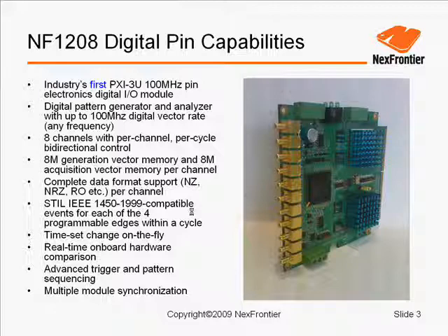IEEE 1450-1999 compatible events for each of the 4 programmable edges within a cycle are supported as well. We are able to do time set change on the fly for this module. Besides, this module is able to do real-time onboard hardware comparison for DUT data that is being captured. It has advanced trigger and pattern sequencing capability, and if you need more channels, it supports multiple module synchronization.